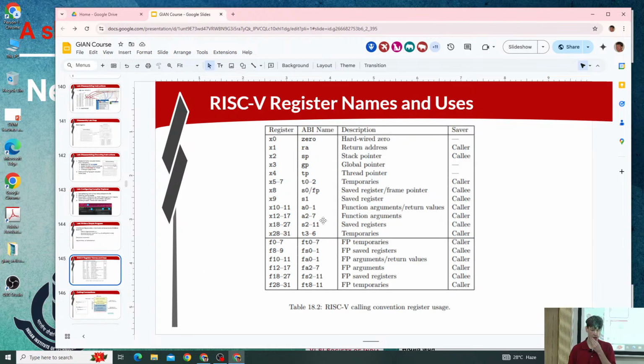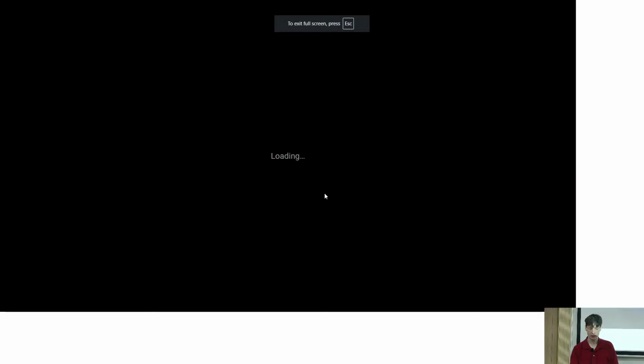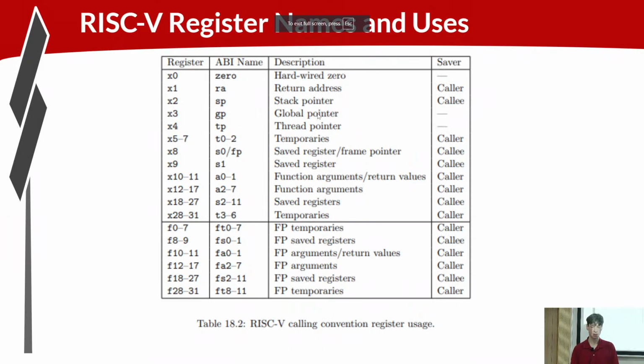All right, so today we'll start here. I pulled up the RISC-V green card before, and we saw this, but just to review, the register file has 32 registers, minus 1 because X0 is a hard-coded 0 value, and there are conventions for the usage of these registers. Mostly it's around calling conventions for one function to call another function. How does it pass values to that function?